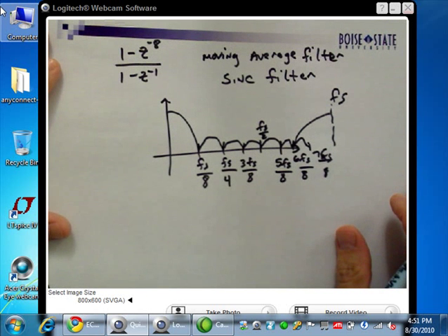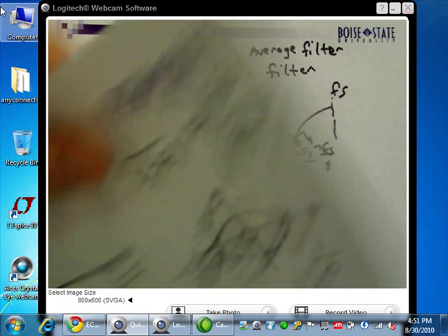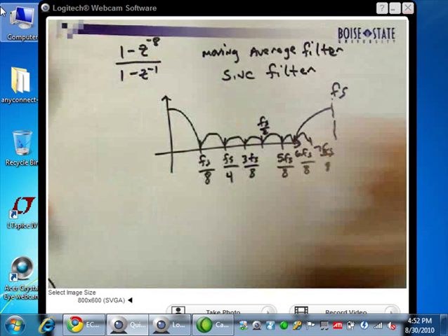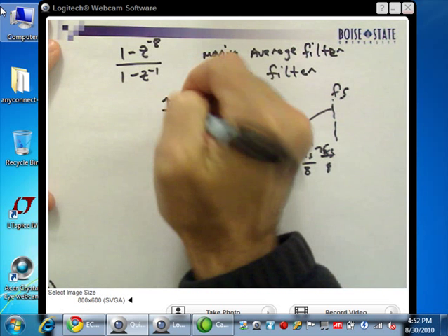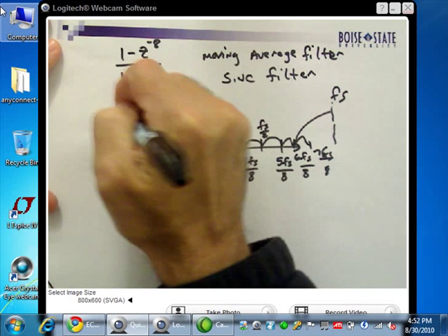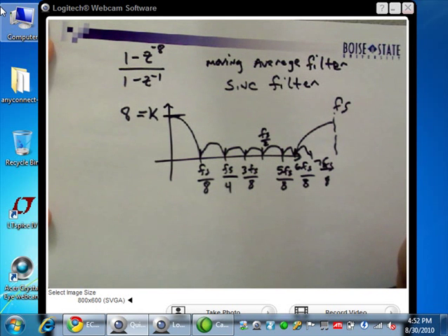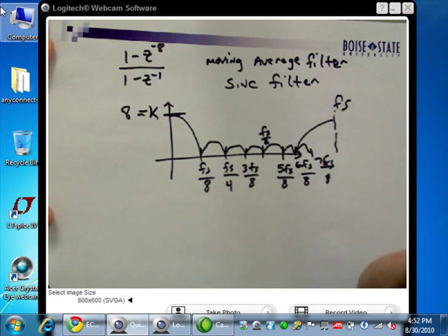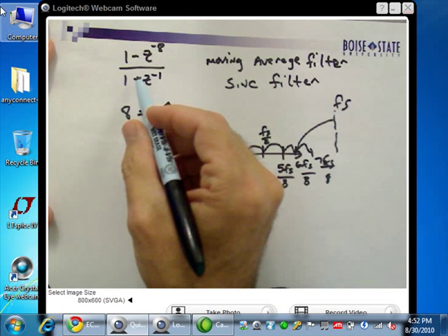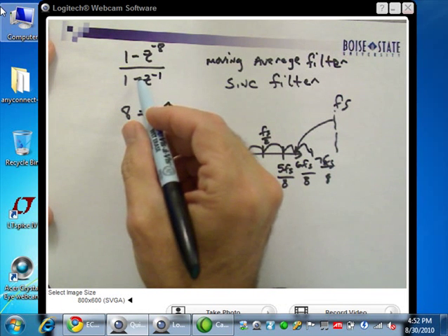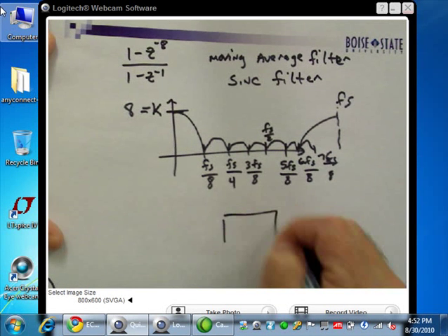Okay, so this is the frequency response, and I'm just going to point out a few things here of this filter. Okay, one is the magnitude here is equal to k, which in this case is 8. Well, we canceled it with the integrator. Yeah, so the 0 at 1 we canceled with the integrator. So if I have this filter here, let me just ask this.